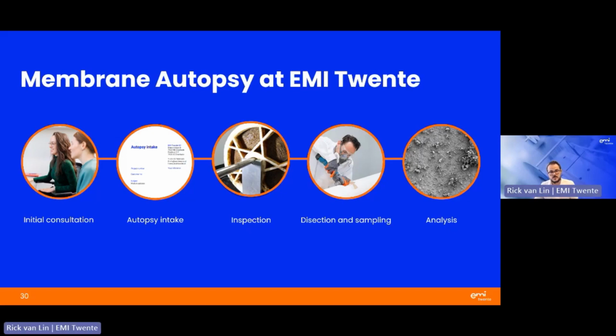Then the autopsy starts, with inspection and documentation of external housing integrity, presence of particles and deposits on the housing, anti-telescoping device conditions, whether there is telescoping or spacer protrusion, what the integrity of the O-ring is, etc.